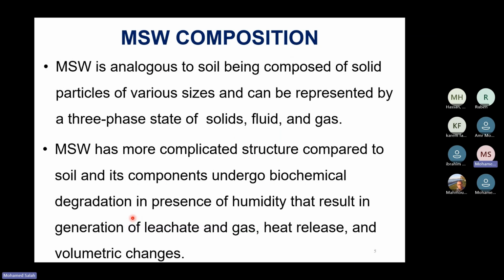So when we think about waste as a material, it can be compared to soil, being composed of solid particles of various sizes, and it can be represented by a three-phase state of solids, fluid, and gas. However, it has a more complicated structure compared to soil, mainly because the components of the waste undergo biochemical degradation in the presence of humidity.